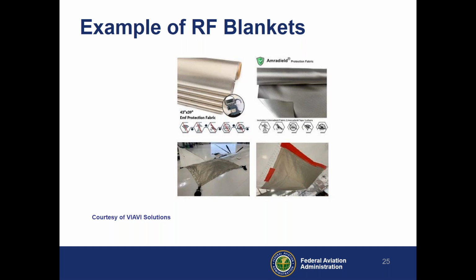At this specific location where you see that RF blanket with the suction cups, we had the hangar door open, and we had actual line of sight to an ADSB ground station, which was, I believe, a little over a quarter mile away. So it was fairly close, and we coordinated this test event with the FAA. We did some testing without the blanket, we did testing with only a coupler, and we did testing with the coupler and the RF blanket material to prove that it would work.